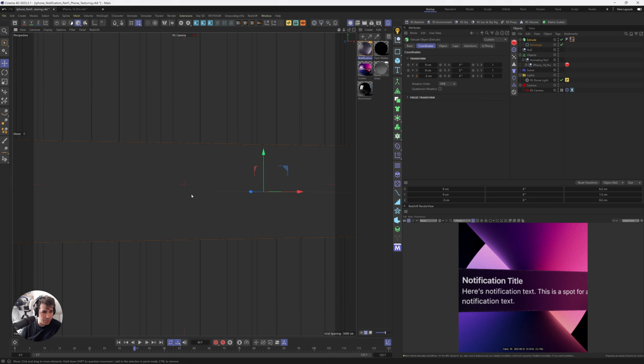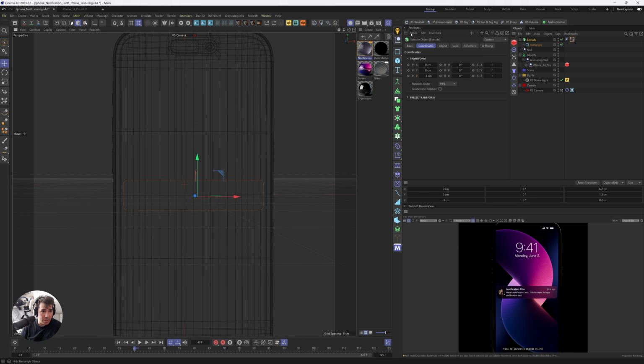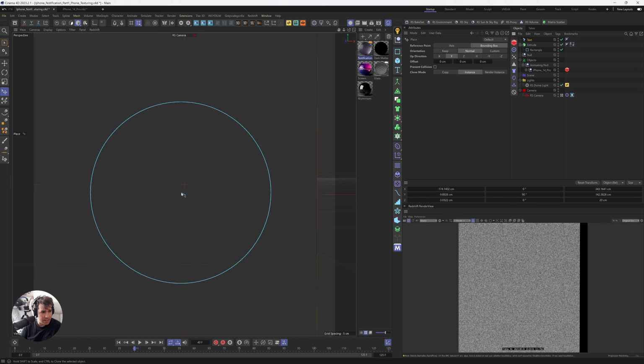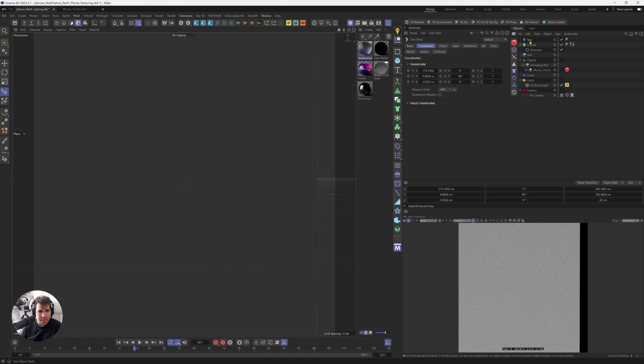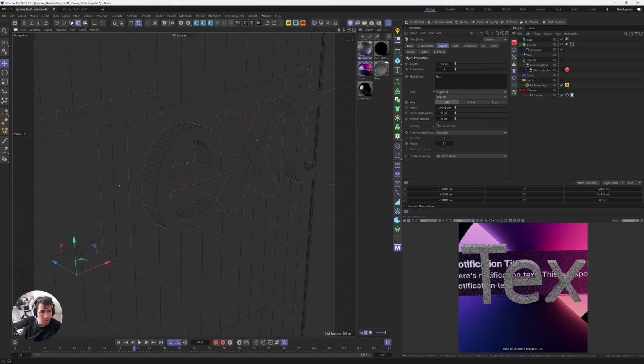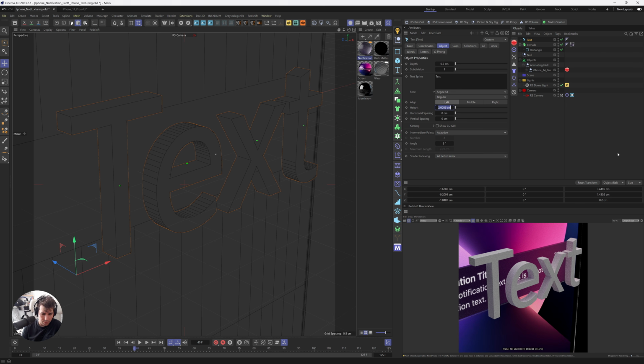And what you want to do is basically bring the text in. So I'm just gonna, not the text line, just the regular text. Just make sure you have a regular text, because there's two options here, text line or text. So you want text, and I'm just gonna apply this text. So I'm gonna put the placement tool and highlight the text over that object and make the text way smaller. So I'm just gonna take it down. So we have a text depth 0.2, and we have a height of 1.